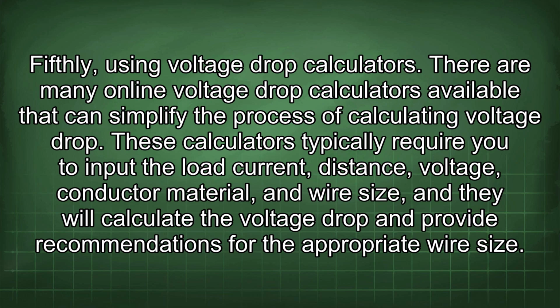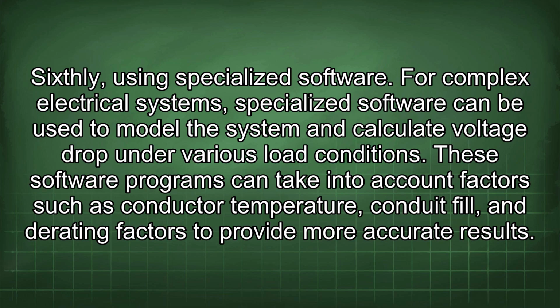Fifthly, using voltage drop calculators. There are many online voltage drop calculators available that can simplify the process of calculating voltage drop. These calculators typically require you to input the load current, distance, voltage, conductor material, and wire size, and they will calculate the voltage drop and provide recommendations for the appropriate wire size. Sixthly, using specialized software.